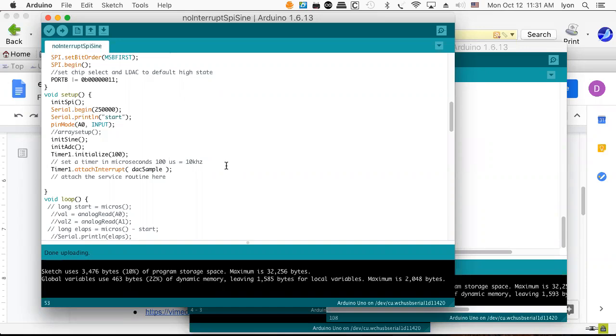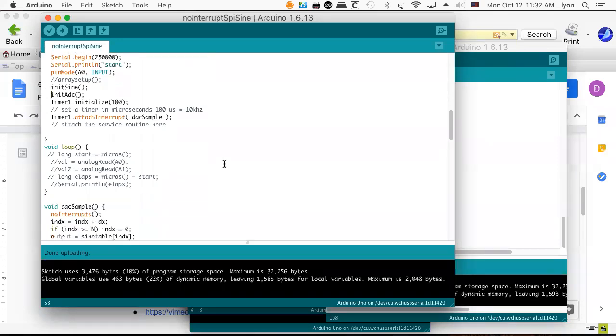And you know what happens when you're doing things where you might interrupt a waveform generation, like a nice fine sine wave like this, is you'll get a glitch. And you want to avoid those glitches. And that's why you want to control when outputs occur on the DAC and when interrupts can and cannot occur. And so this is quite nice because now you've got, let me turn this down now because it's annoying. So now you've got a nice interrupt-driven system.